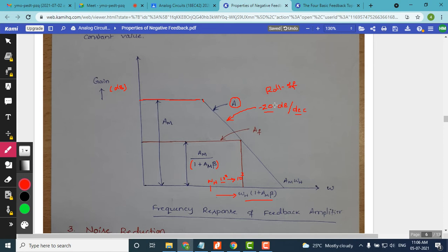For second order and subsequent orders, the roll off rate will be more rapid. For second order, it is going to be 40 dB per decade, and for third order, it is going to be 60 dB per decade. So the order should be multiplied with n here. n equal to 1 means 20 dB per decade, n equal to 2 means 40 dB per decade, that is a second order system. When the filter order keeps increasing, the roll off rate also keeps increasing, but the transfer function becomes complicated when you go for higher order. We will see these things while designing the filter, in upcoming modules.